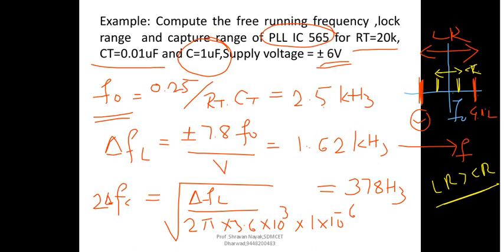How do they decide the output of the voltage controlled oscillator to be tracked to the reference signal? Then how is the low pass filter realized here, using the external resistance, the fixed resistance component, and the external capacitance? And we have looked into some simple numerical examples here.